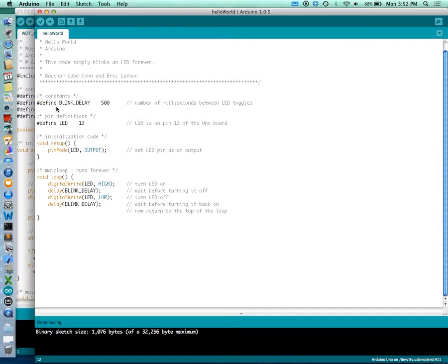Actually, you can do C++ code in Arduino, but it's not considered Arduino-esque to write C++ because when you have classes, you're using a lot of memory that you don't want to. Even though it's not a whole lot, you've only got 2 kilobytes to work with. So when you create a class structure and it's saving everything in memory, it's still eating up a lot of memory that you don't have on an Arduino. You still can use it. It's absolutely fine. You just need to be aware of how to use it.